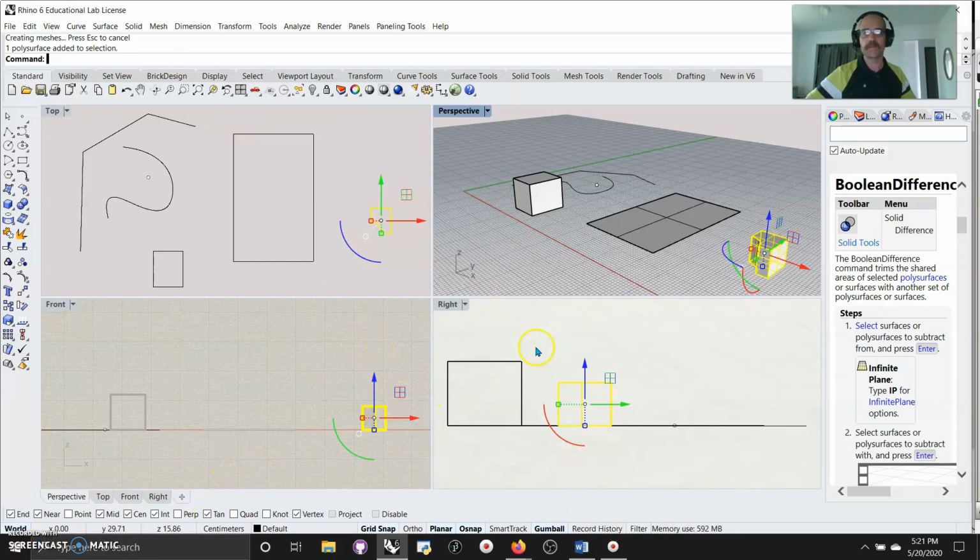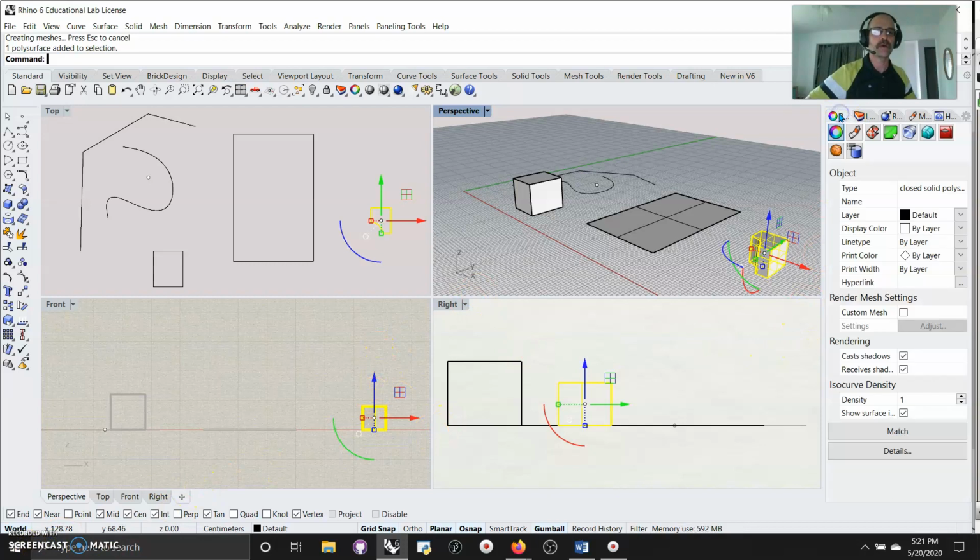That's a lot of information right now. We're already above 5 minutes. I've shown you what to put in this corner over here on layers. Down here, you're going to have your object selects. You're going to have your grid snaps, your ortho, XYZ, your planar, your object snaps, a smart track if you want on or off, a grid snap if you want on or off, a gumball if you want it on or off. You can do amazing things with this gumball tool. Control, select, edit, and grab things and move edges and points and vertices and sides and deal in meshes.